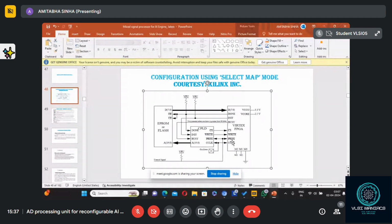So the configurable clock, prog, write bar, chip select bar of the FPGA, that is understood now. In most FPGAs you have to consult the manual because slight variations will be there, but the basic signals will be common, like chip select bar, write bar, program bar, configurable clock. Busy will also be there. When the FPGA is busy, meaning it is getting programmed, the busy line will be high; then when the busy line goes low, the next byte can be stored. In that way the things will be done.